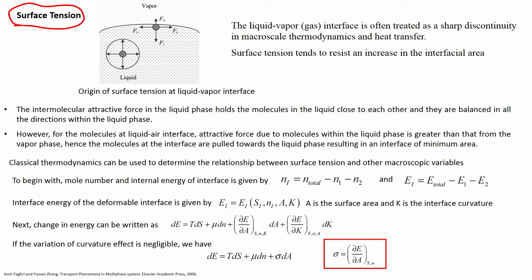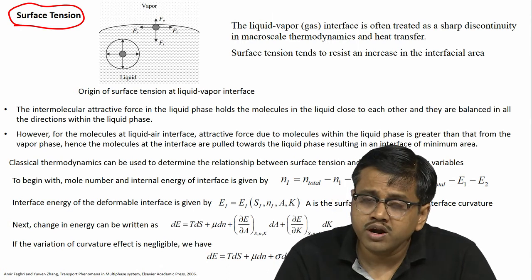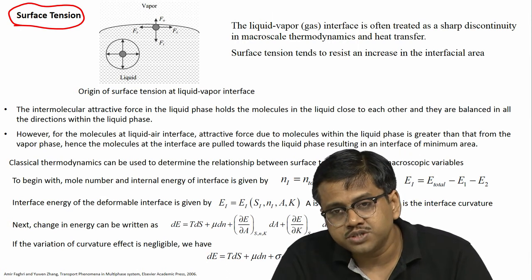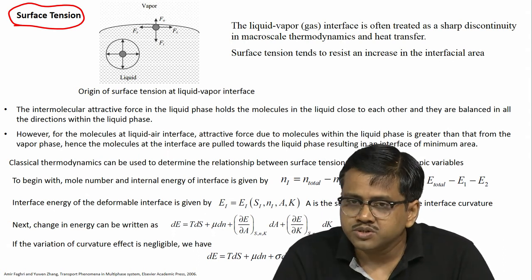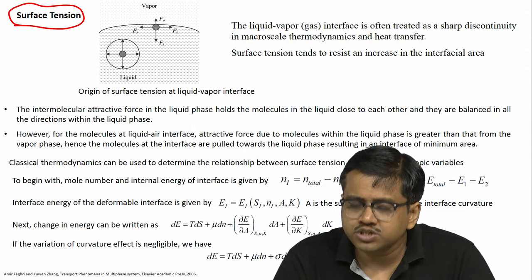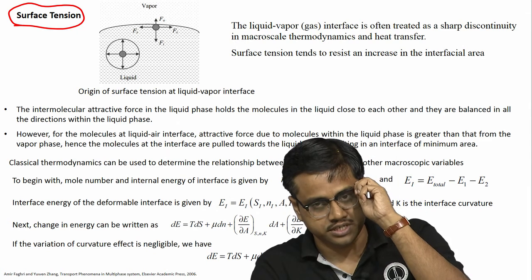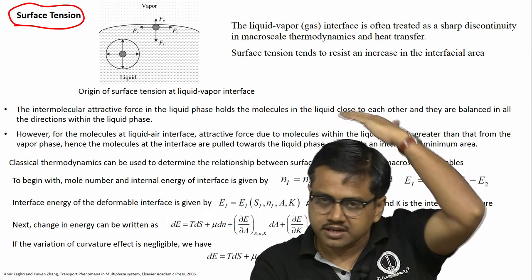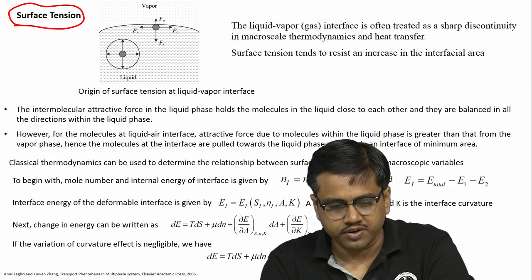Because, as I said, most of the convective heat transfer problems that you will see involve droplets, and there will be flow around a droplet. The droplet will try to retain its shape. In sessile droplets it is also the same. What makes the droplet hold its shape is attributed to surface tension. So, let us look at how surface tension is useful here.